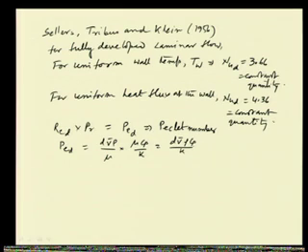So, if we rewrite by some rearrangements, then it becomes rho V bar Cp delta T by k delta T by d. Now, if we see the top and bottom portions, numerator and denominator, we see that the numerator is nothing but heat removal by bulk flow, and the denominator is heat removal by conductive flow.